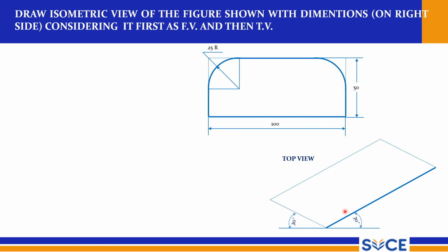So now you can use the four center concept to draw this curve, right? This is the curve. You can use a four center concept. Now I am dividing this into two parts, right? I am dividing this into two parts, and now this is my diagonal, smallest diagonal, and I have used these two, right? This is only half four center I am using, right? So this is the center now, right? Now this much as radius, you can draw the arc, right?